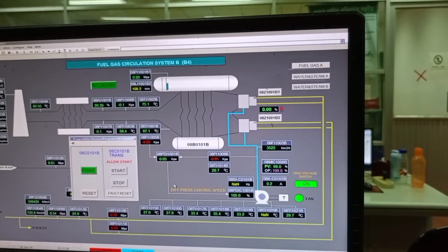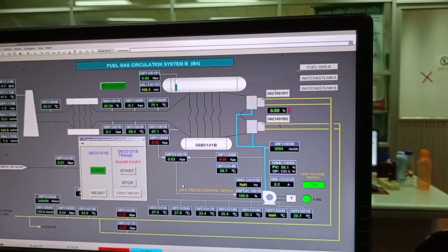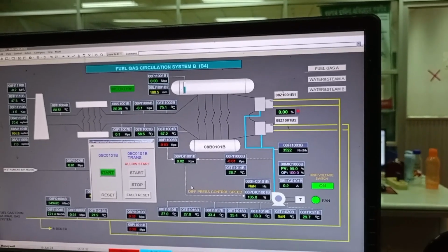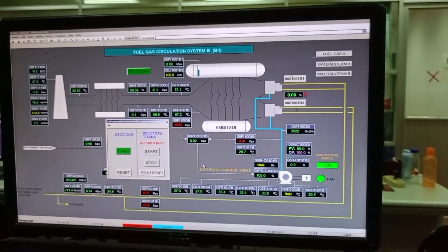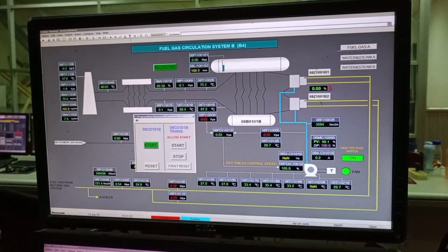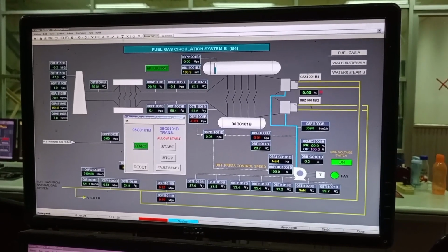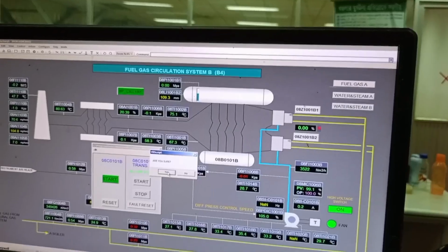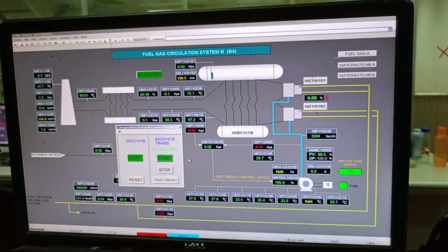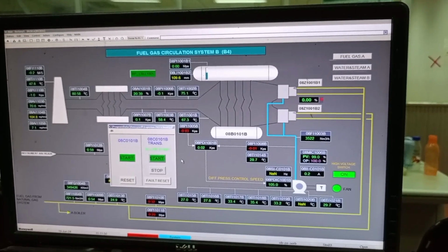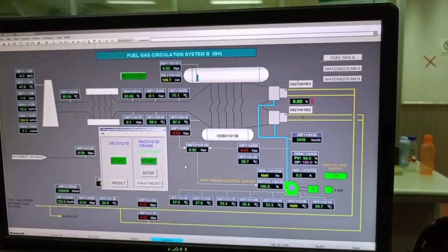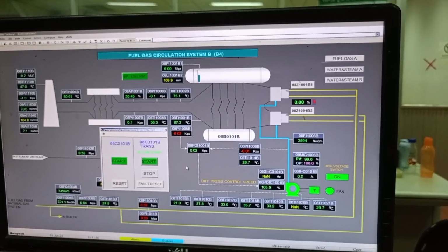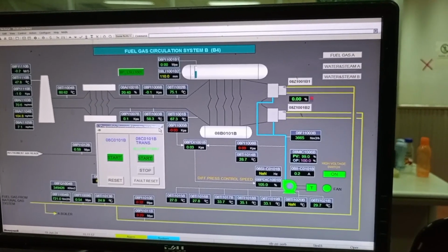As the boiler is controlled by the DCS system, everything is smoothly controlled by operation from a PC. And from the burner management system, there is a 3-element system, that means steam flow, water flow, and water level, drum level.